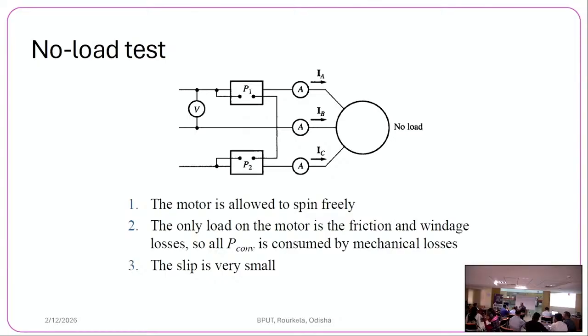The point is that when you apply DC, the inductance will have no reactance, because frequency is not there. When you apply AC and you go on increasing the frequency, the reactance will increase with frequency. And whenever you make a resistance, it will have some inductance also. So because of this inductance, the reactance increases. Because reactance increases, the current tends to flow more and more on the outer surface, not inside.